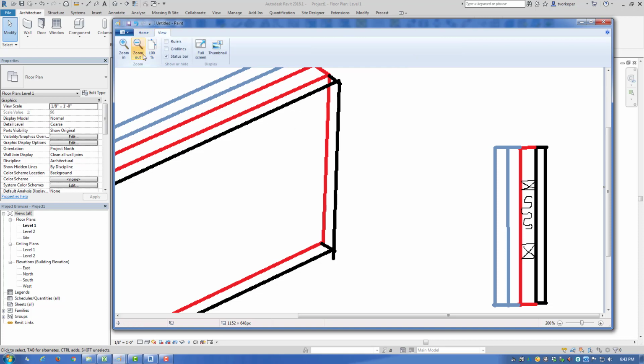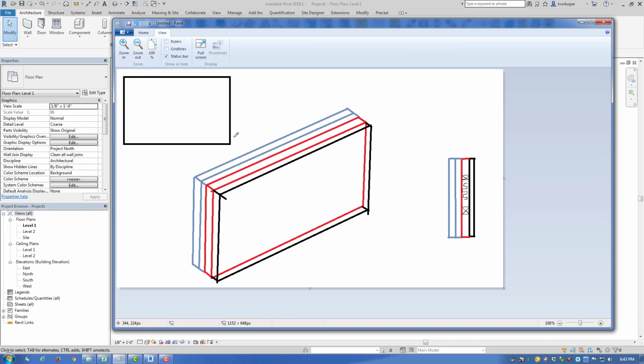In addition to that, Revit wants to look at surface patterns. So if we're looking at the gypboard layer, Revit wants to show the surface pattern to the user, and so we might define the gyp layer material as having stipple all throughout the layer. So whenever we see the face view of this gypboard layer, Revit will show us a stipple pattern to represent gypboard.